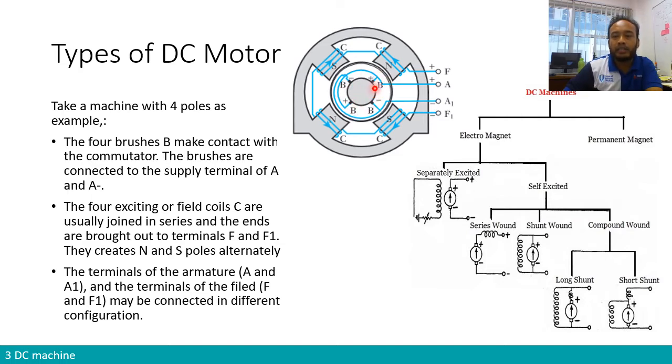The brushes are basically the component that sends the current from the power supply into what we call the commutator. So we've learned what a commutator is in the first week of the discussion on DC machines. The current comes from a power supply and goes into these brushes, which are in frictional contact with the armature, with the commutator.